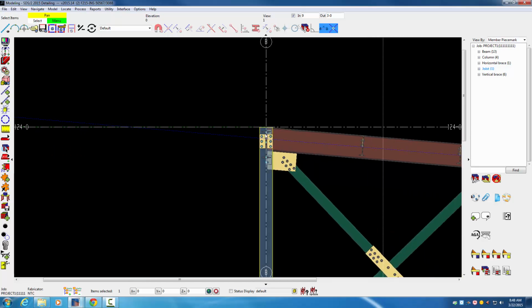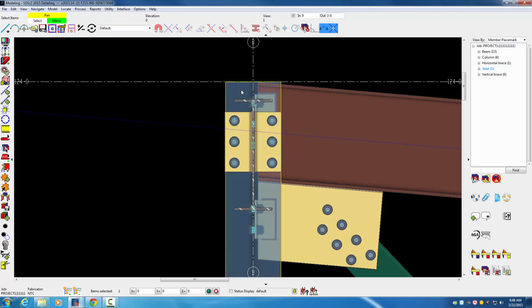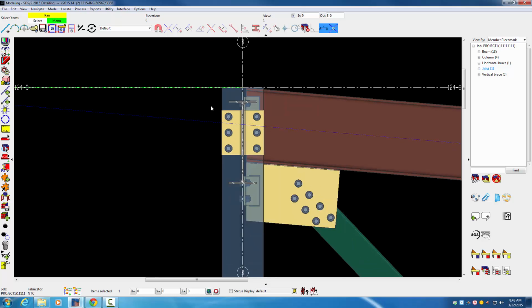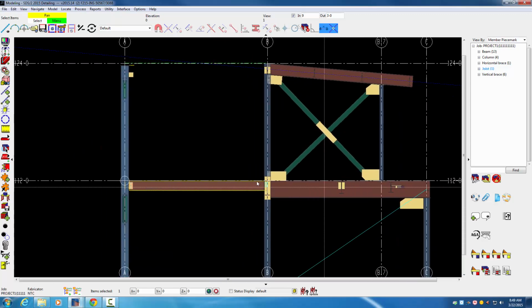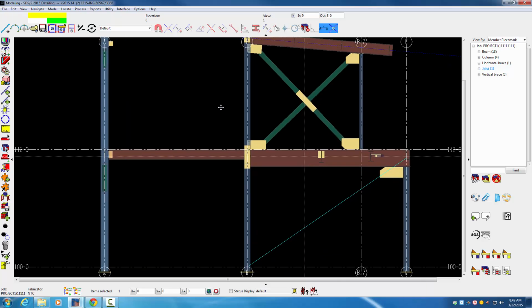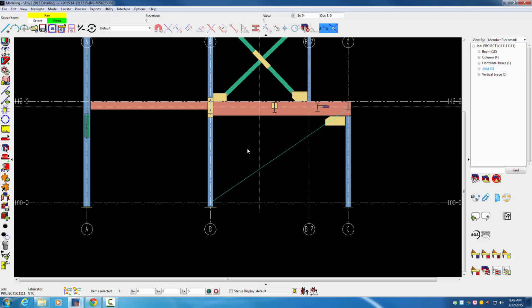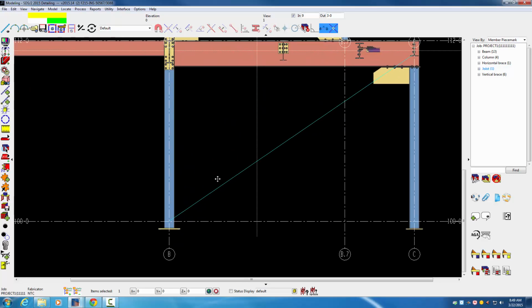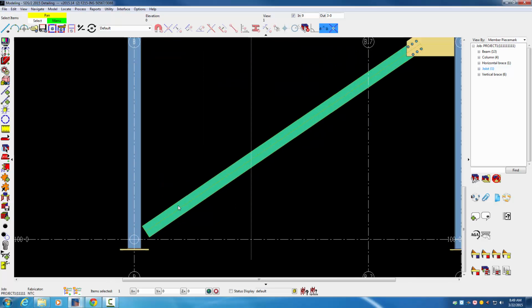On the other end of the bar joist, when it frames to the column, right now there is not a connection. We're going to come back to this connection in a little bit, so we'll skip that for now. The beam here, we looked at that on plan view. That's good. So here I'm going to do all solid, and this beam right now has failed, so I'm going to hit process here, get it back to solid, but the beam has failed, and it should be failed on your model also.